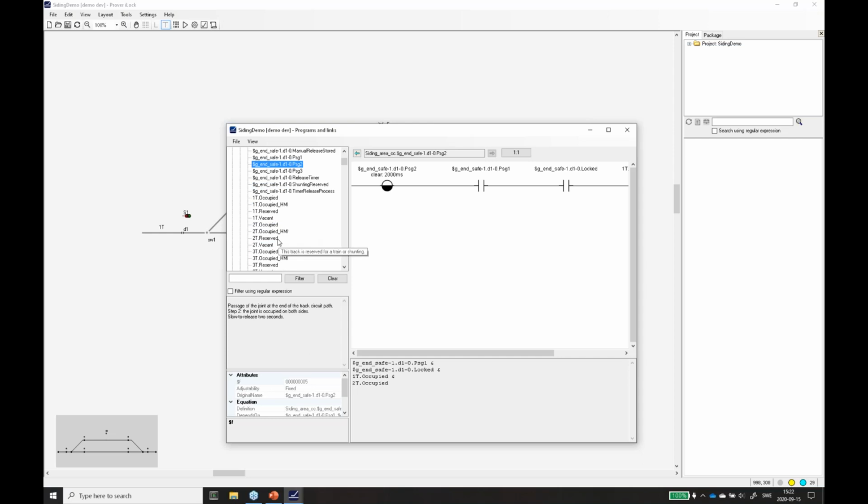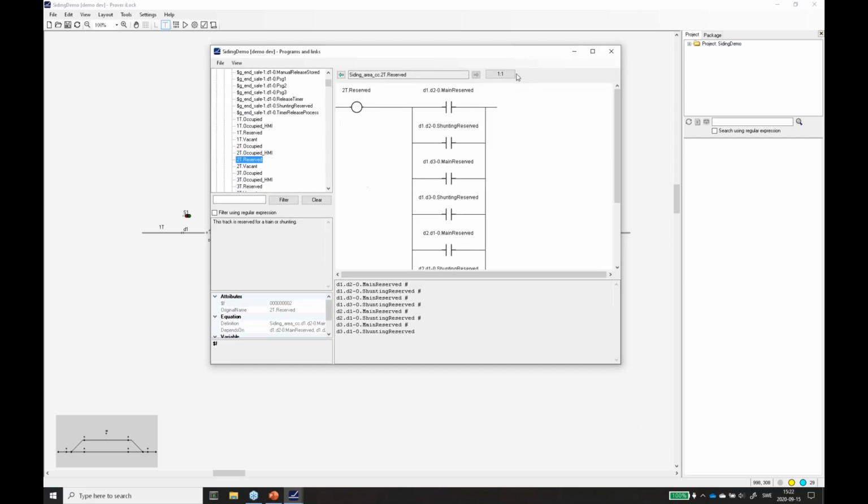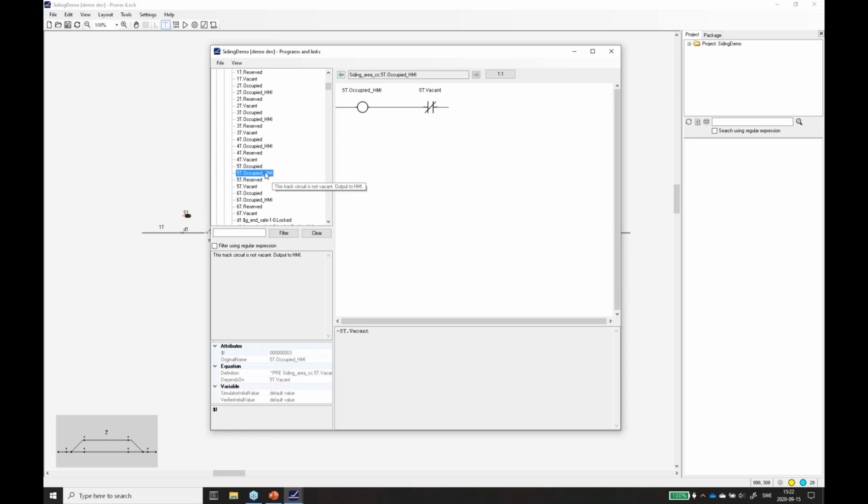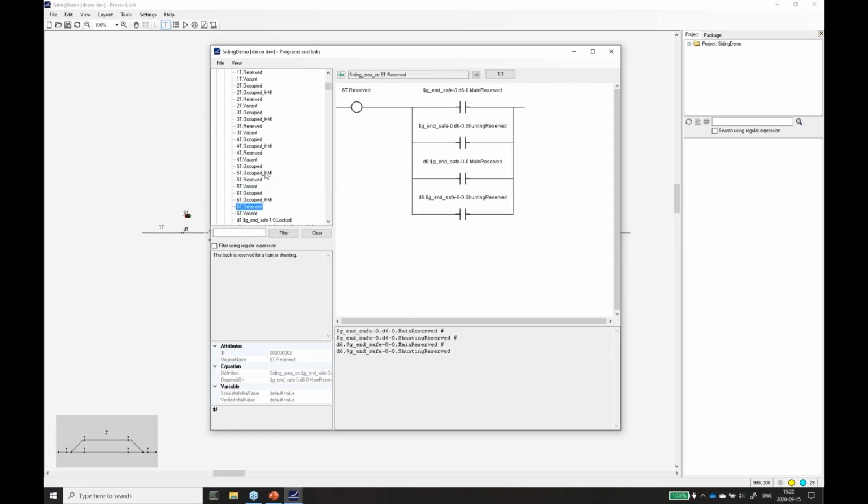As is common with interlocking systems, they are typically Boolean, but you can imagine also having other signaling systems like zone controllers for a CBTC, for instance, where you have also some integers or even floating point numbers and arithmetic operations on that. Then that will be included as well. But right now we are limited to the Booleans in this example.